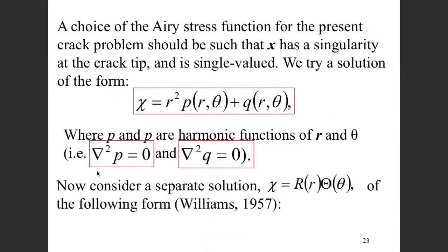And we also know that there's a singularity at the crack tip. So generally the time-honored method of solving PDEs analytically is guess and check, right? Come up with solutions of certain forms. The fact that it's a linear equation helps us a lot. That means we can put it into some standard lookup.